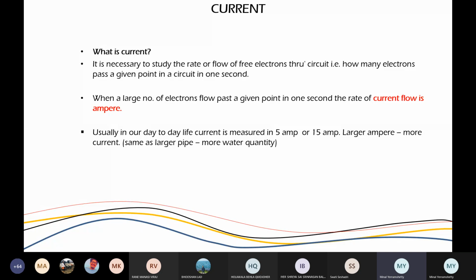That's why your AC will also have 15 ampere. So please understand the difference between three phase and ampere. Three phase we use where the load of the entire building is so heavy that a single phase would burn out. So then what I do is, if my load is say 900 something, I can put it on three phase, and I can say 300 goes to this phase, 300 to this, 300 to this, and accordingly I'll wire my entire building.